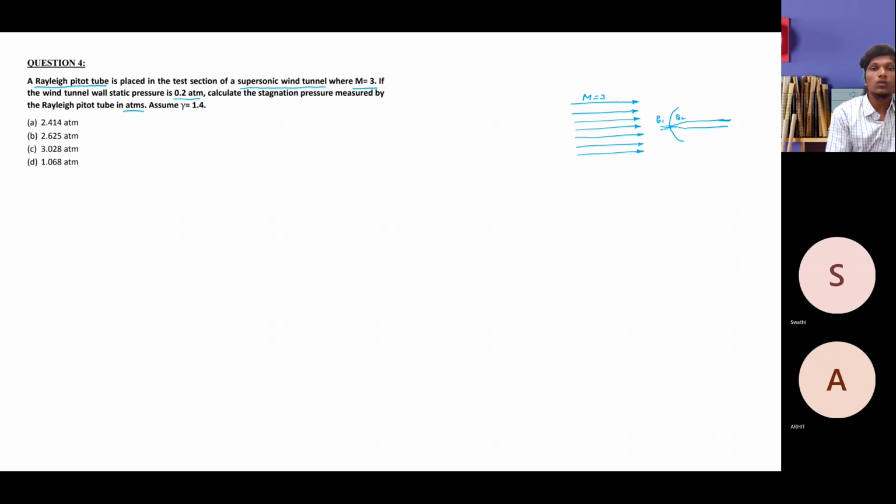So the Pitot tube also measures this stagnation pressure, that is P02 instead of P01. But our free stream is coming with the stagnation pressure of P01. So we have to be careful about this particular point while we are trying to measure the supersonic flow characteristics.